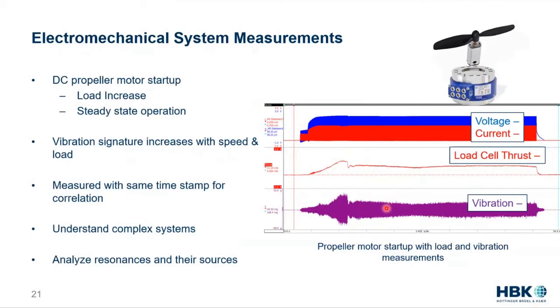but it's really unique being able to look at these two values, high frequency current as well as high frequency vibration on the same timestamp, and start to analyze resonances and start to understand these complex systems. The systems we've implemented with some of our electric aircraft partners have almost all had a high number of accelerometer channels for understanding the vibration of the system. It's unbelievably important to durability, fatigue, as well as the experience of the vehicle.